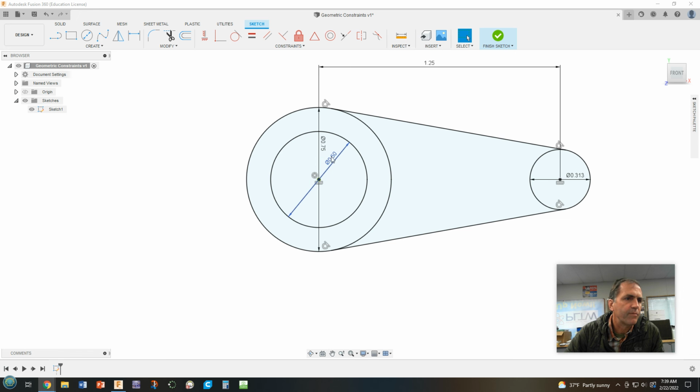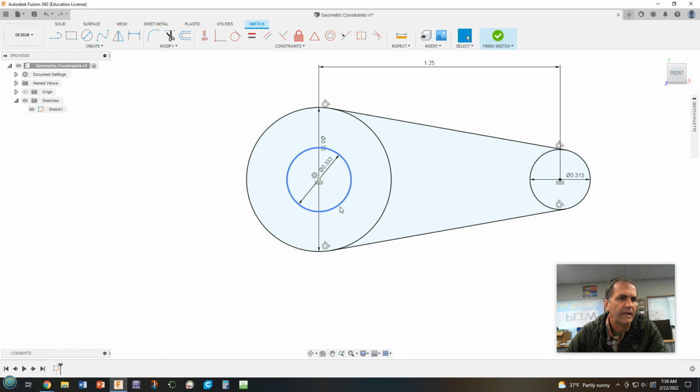Take that back. If you already made it, double click on that. And let's make it 5/16, which is the size of the spindle that's going to be there, but I want it a little bit bigger than that. So let's make it plus 0.02. Make this authentic. Okay.